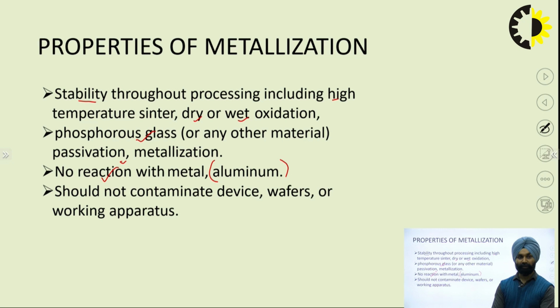Lastly, most important is that it should not contaminate our created device, wafer, or any operators that are used for the creation of the wafer. We have done all the previous steps in a very clean environment, as we have discussed with in situ cleaning, and the highly contamination-free environment. We have discussed the vacuum pumps that give an inert gas environment, the ambient control system. All these systems are used so that there should not be any contamination in the device.